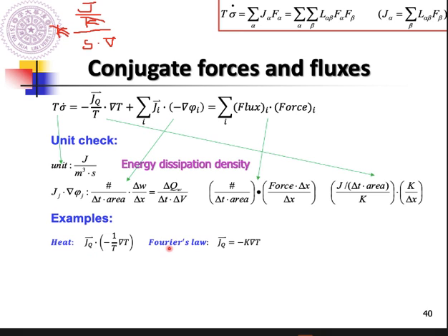Based on your previous knowledge, we learned that Fourier's law helps us know the thermal conductivity, expressed as the heat flux equals minus thermal conductivity times the temperature gradient. So as long as I measure the heat flux, then divide by temperature gradient, I can know the thermal conductivity of this material. So this is what Fourier's law tells us. By using this law, we can calculate the thermal conductivity of your materials of interest.